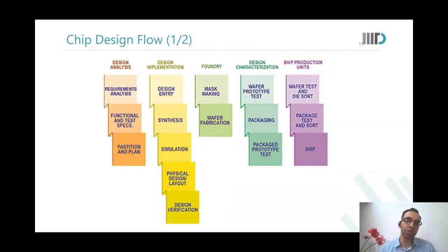This is hardcore implementation. And once that implementation is done, you will simply do a design verification that whatever chip I have now designed, I have now implemented, is in line with the design specifications that I had. Okay. And then what we would do is we call it a tape out. Then we tape out our chip and send the design to the foundry. In the foundry,